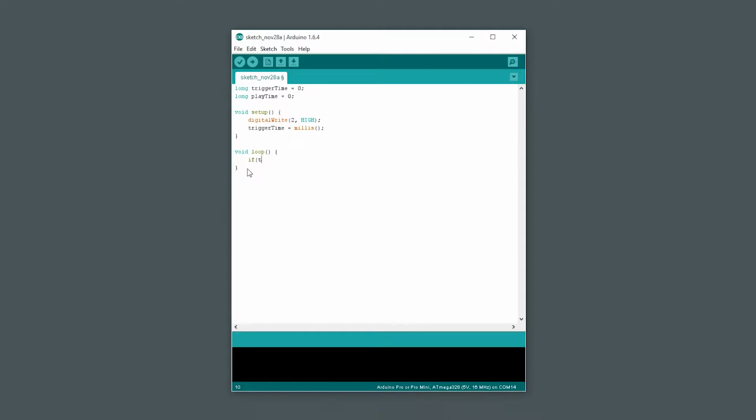Now I'm not going to use the busy pin on the device to tell me if it's actually playing the file. I'm not sure if it reports that it's busy as soon as it receives the command to play the file or after it actually starts playing it. What I'm going to do is monitor, using analog read, one of the speaker pins on the device. So as soon as that actually starts making a sound through the speaker, I should see a spike in the voltage on that pin, and that's when I'll know that it's actually started playing.